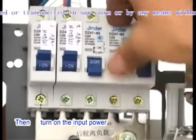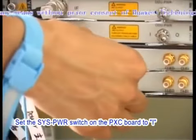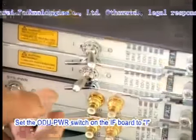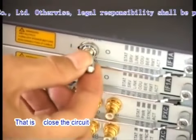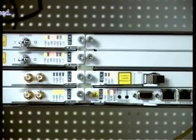Then turn on the input power. Set the system power switch on the PXC board to I. Set the ODU power switch on the IF board to I, that is, close the circuit. The equipment needs 3 to 5 minutes to fully start.